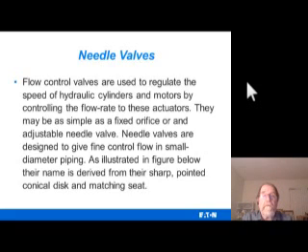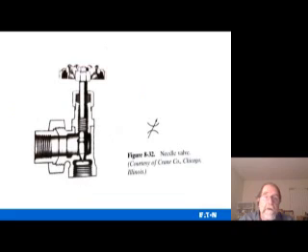Again, that's similar to what you had in carburetors. You guys remember what those are. If you look, I think this next drawing here has it. See that right down in here is a little round tapered hole that this pointed object flows in. And you turn that knob and it pushes it back down into that hole and it stops the flow. So you can get precise flow.